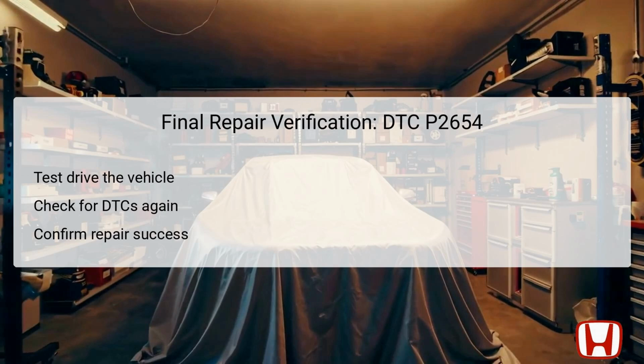After completing repairs based on previous troubleshooting steps, it's important to conduct a final verification. This involves taking the vehicle for a test drive under various driving conditions to ensure that everything operates smoothly. Following the test drive, recheck for any DTCs using the Honda Diagnostics System, HDS. A successful repair is indicated by the absence of DTC